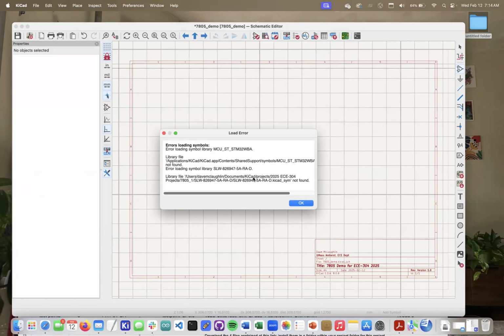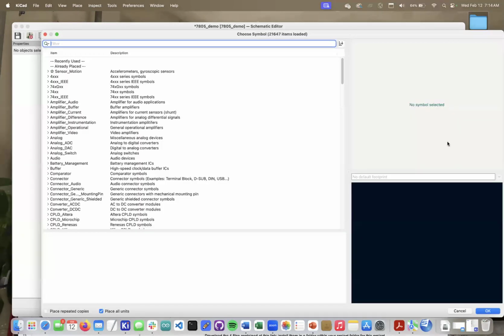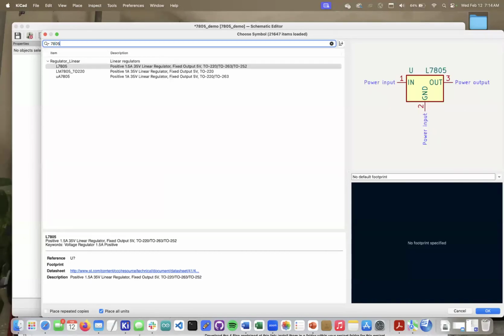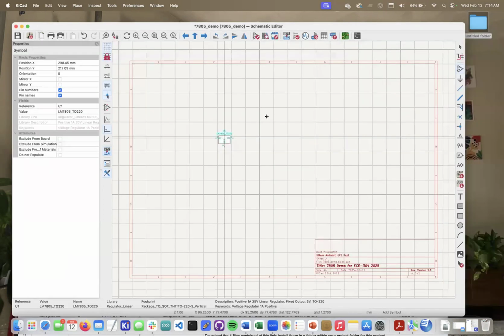Some of these are things that we will care about, but I'll show you how to deal with it. So I wanted 7805. Just typing that in, and it's the LM7805 TO220. And we saw that in the spreadsheet. I'll go back and show it to you, but I'm just going to say okay, and I'm going to drop it right here.